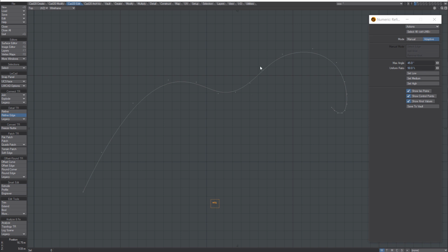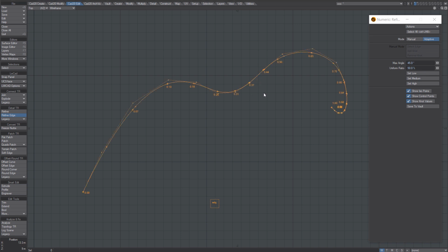The refinement operation is a non-destructive, non-precision-losing operation. So after more knots are inserted into a curve, mathematically it is absolutely the same precise shape as the previous version of the curve, and it is non-destructive. The reverse operation, the automatic reduce operation, will be upgraded in the next version. It is right now priority number one in the next development to do the reverse operation on this essential refinement.